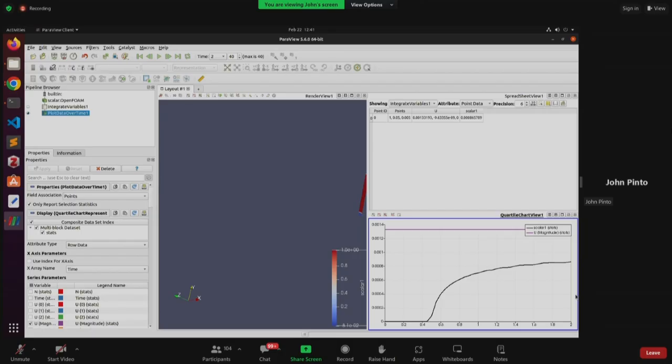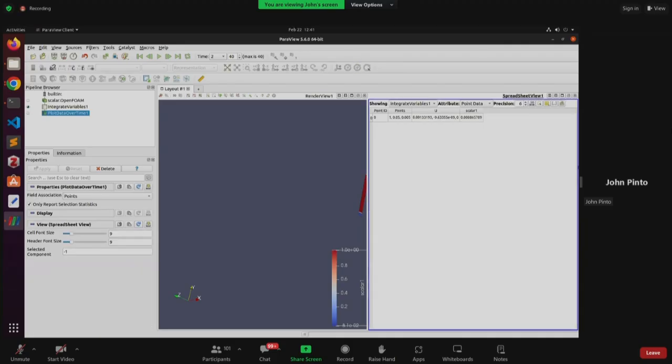Because of that parabolic section, the amount of scalar reached at 0.5 second will be low, and that will increase. So here you see somewhere around 0.5 second is reached when we start to sense the scalar. This will become more and more accurate if you refine the mesh further and use some higher order schemes. This is what you can also try exploring on your own. So this is what happens when we use a parabolic profile.